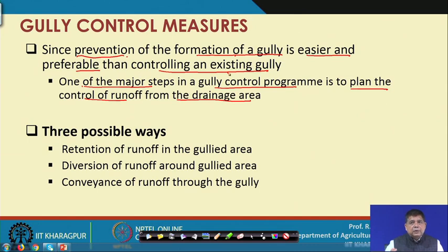And as we know the entire process of gully formation, we have to go into the basics of soil erosion mechanics. You remember that we started with soil erosion and we said that it all starts with the raindrop splash erosion. Whenever raindrops fall, there will be splash and the loose soil particles will be spread on the surface. When the rain continues, after satisfying the infiltration capacity of the soil,